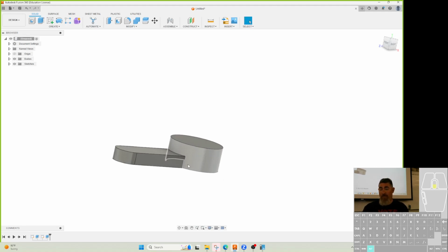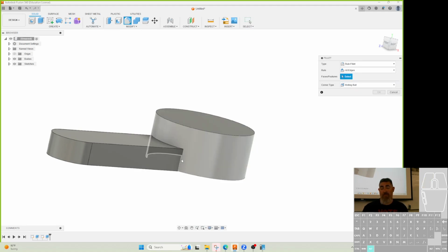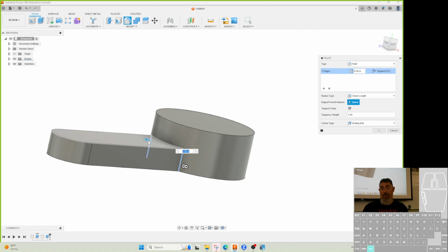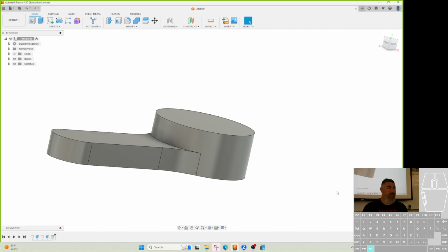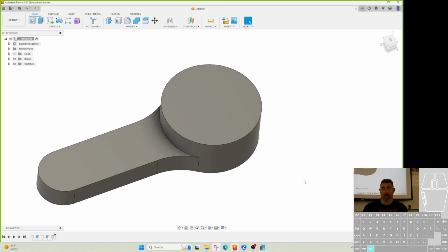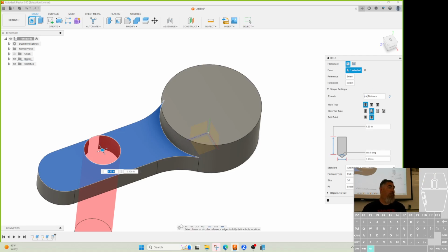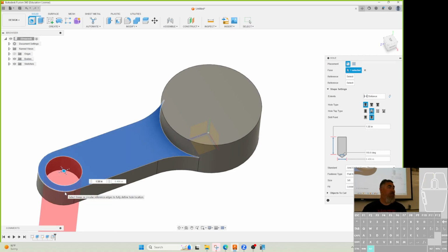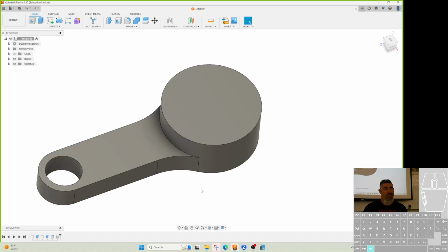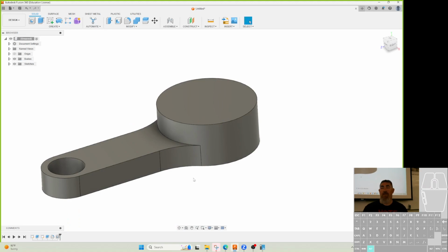Also, no fillets there, right? Because fillets there is really just do a regular fillet, bam, bam, and the fillets are there, right? So, hole here, hole, click anywhere, doesn't matter. Now pick that edge, and it centers it up. Change the settings, okay? So, remember, when you're placing your thing down, it doesn't have to be perfect. You can always move it around, okay?